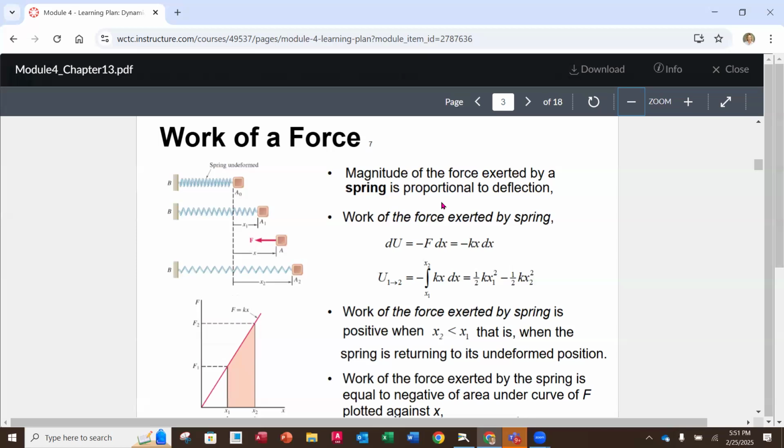And while we're in what we call the elastic area of our spring, that means that when we apply a load to it and we let go and take that load off, it's going to bounce back to its original shape. Once we get beyond what we call the elastic limit, just like in strength of materials, you are inducing permanent deformation, and you no longer are going to get the performance out of that spring like you did before.